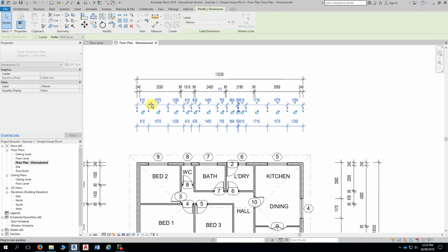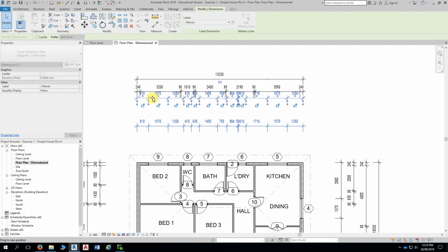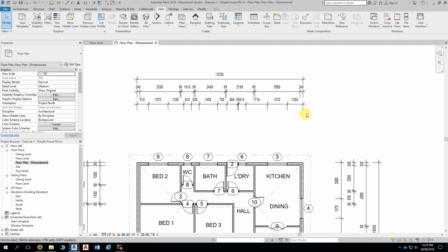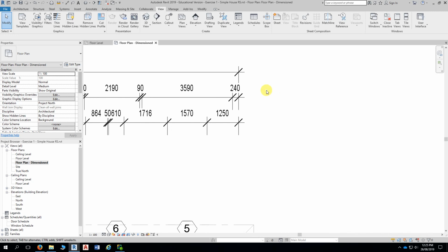And if I bring this dimension set up, I should get the, so yeah, there it is there. It's very, very faint on my system. There it is there. Can you see it? Just out to the left here. Okay, so just bring your dimensions together, and ultimately that dashed line, when it appears, is your dimension snap spacing. So each of my dimensions now is 10 millimeters from the previous. So they're all the same.